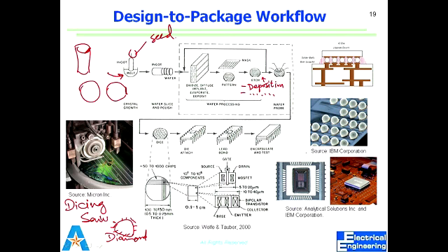Once I draw it, silicon atoms are going to get cold, they're going to get solidified. But during this process, they're going to follow the pattern of the crystal of my seed. Right? Once I draw it out, I draw a big cylinder with it. The size of the cylinder depends on how fast I draw. But that, what you call an ingot, the cylinder of silicon, is now single crystalline, following the structure of my seed. So once you get that out, it's a cylinder, we polish it, we bring it to size, cut it from a side.